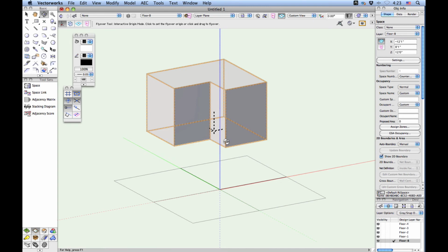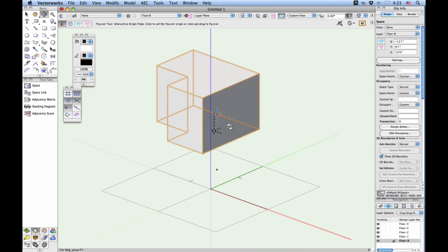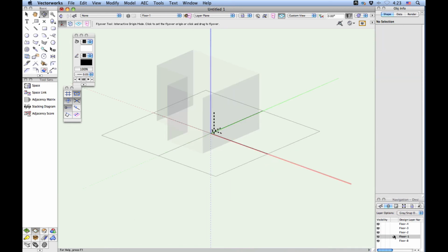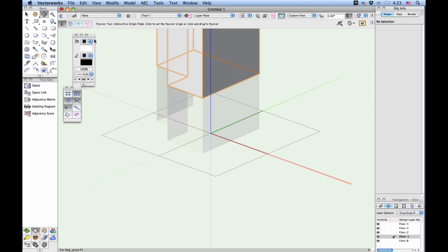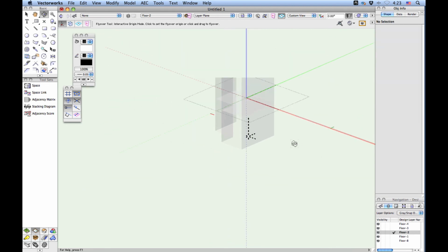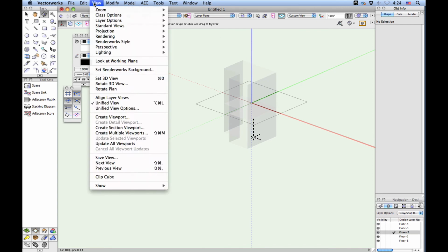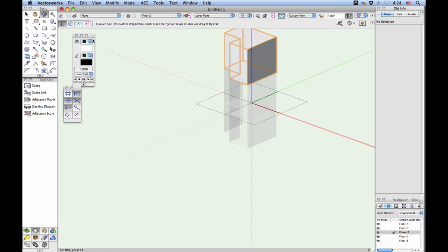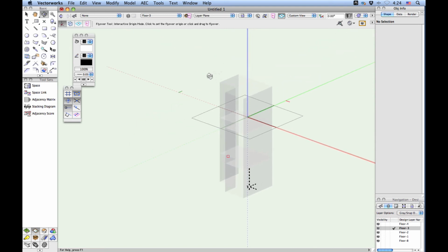Now what I want to do is add the others, so I'll copy this, and go to the next layer and then paste in place. What that means is keeping the same registration now, so I'll choose edit, paste in place. We should see the next one stacking on top and so forth, so I'll just go ahead and zoom out, make the next one visible and active, and then choose paste in place again, and you'll see each time as I go up. So I can get myself a building stack this way.